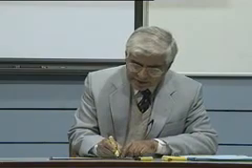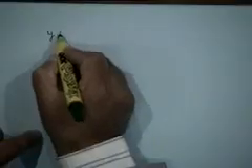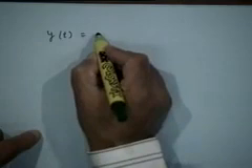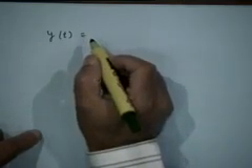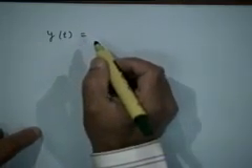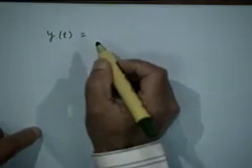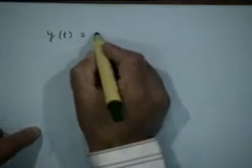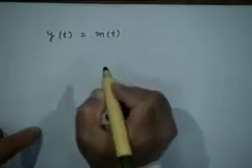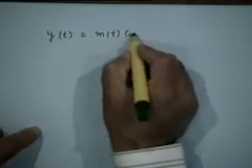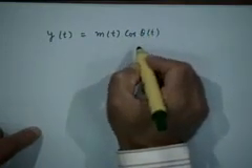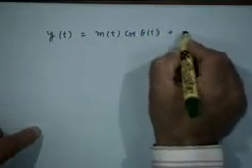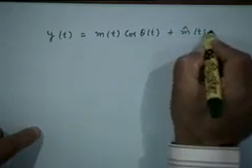Now we were also looking at the demodulation, and when we were discussing the demodulation, we found that the demodulated signal, when you do coherent detection, in the presence of, let's say, lack of synchronization between the local carrier and the incoming carrier, would consist of a component due to m(t) plus a component also due to m hat(t), right?